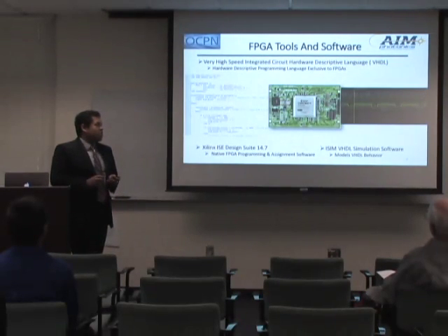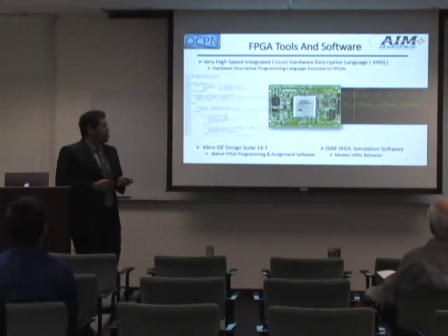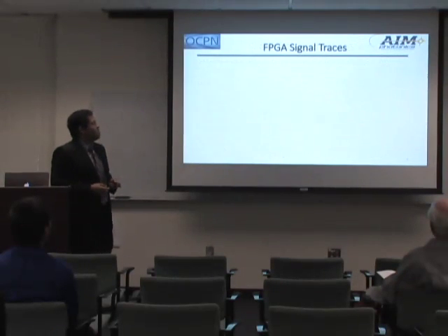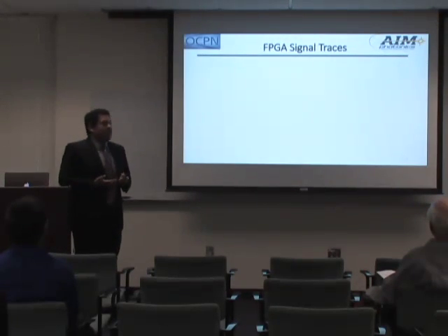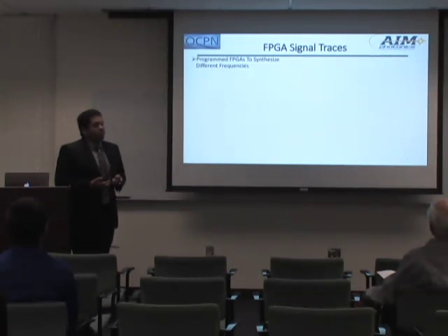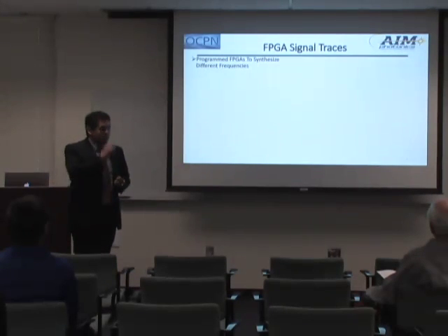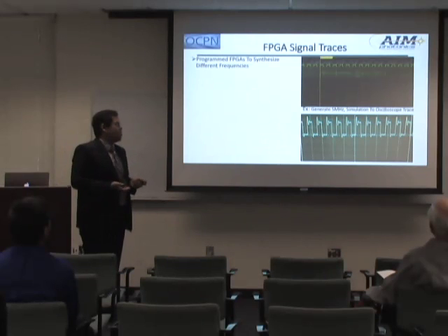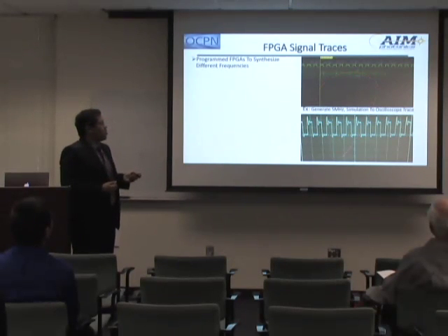But it also has another program called ISim, which works as VHDL simulation software. I can use ISim to model the behavior of VHDL code that I might have written in the Design Suite program. And I actually want to talk about traces now. What I've been working on is programming the FPGA to synthesize different frequencies. I just want to show you an example of one such program that I wrote to demonstrate. On the top here is a simulation trace.